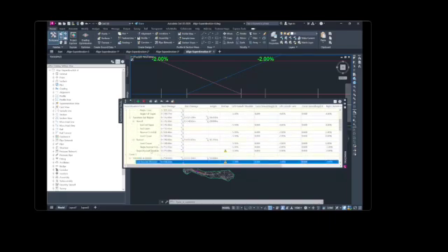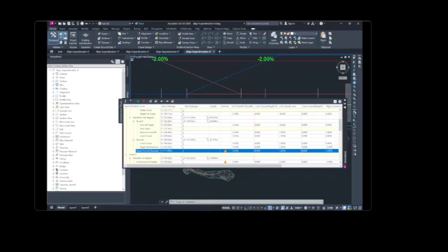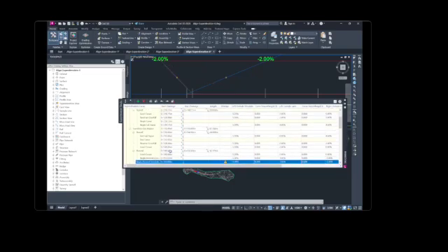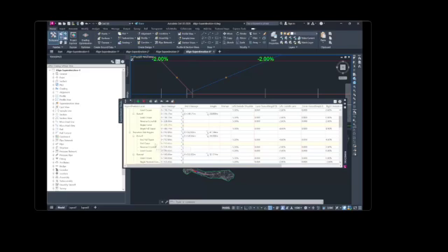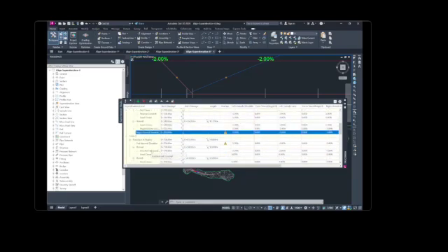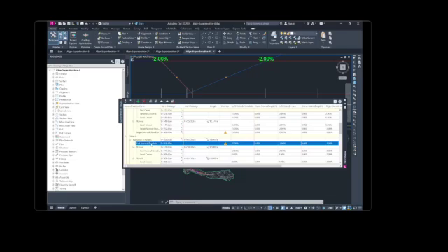We're going to expand curve 2. Now we're editing super elevation stations. Select begin normal shoulder row. Change the start station value to positive 560. Now we're going to remove a super elevation critical station. In curve 3, transitioning region, we click the end normal shoulder, the super elevation critical station is removed, and exit.